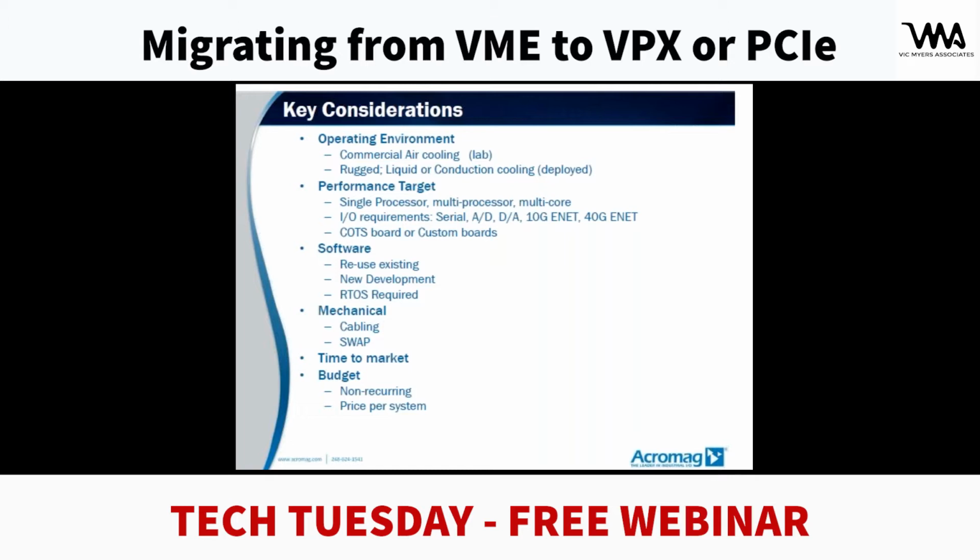Operating environment is a key consideration. One must understand where this system is going to be required to operate from a temperature range, from a shock and vibration standpoint, and humidity. It's key to understand the operating environment, and how a lab unit and a deployed unit, if they're going to be sharing the same environment, and what type of cooling is going to be required.